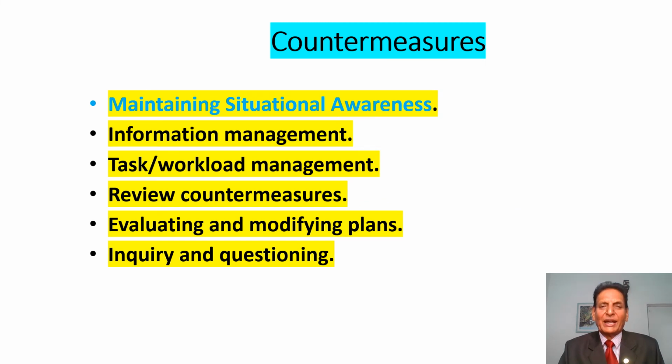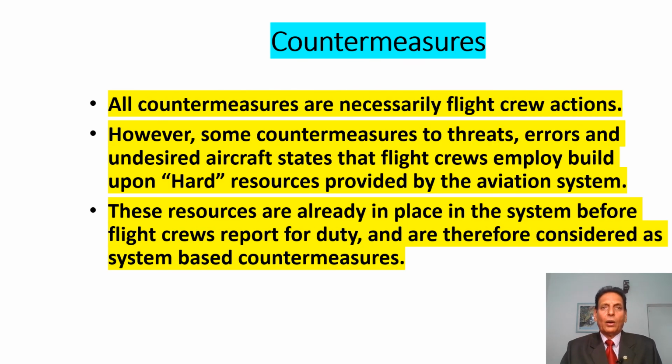Maintaining situational awareness. It is important for maintaining situational awareness that the information management is good. Task workload management is essential. Pilots must review countermeasures. They should evaluate and modify plans, inquiry and questioning. All countermeasures are necessarily flight crew actions.